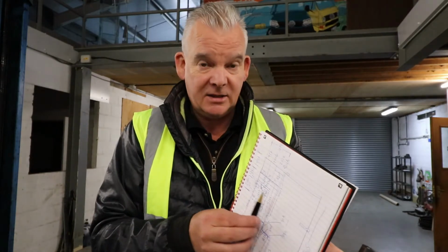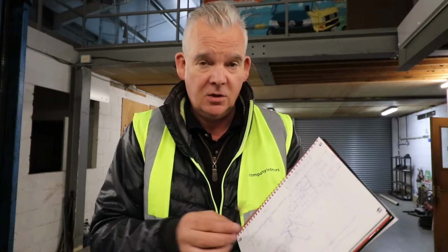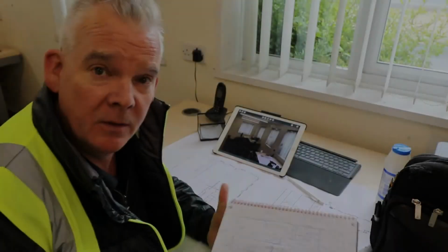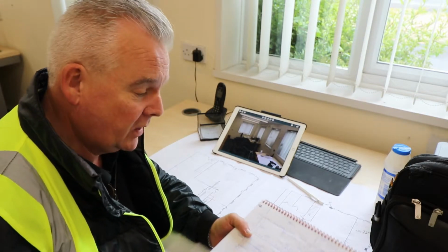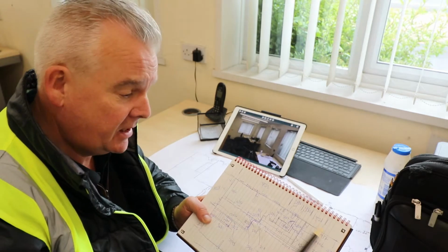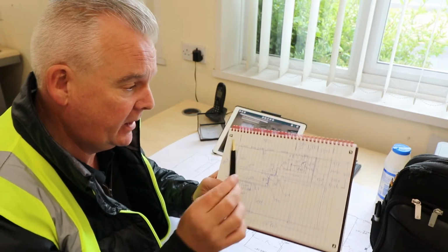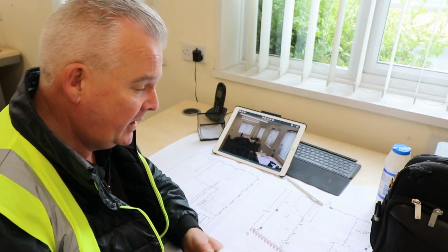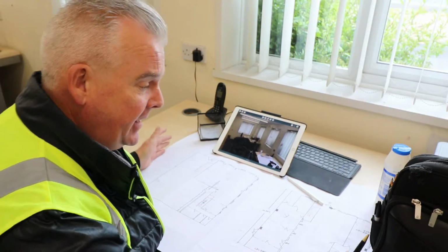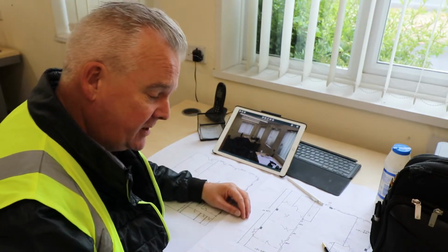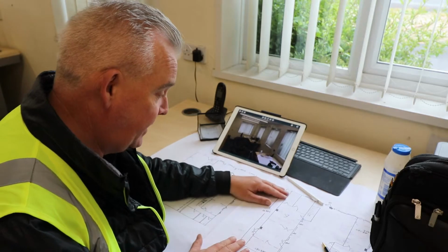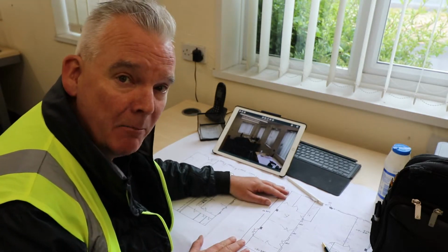We're now just going to go off and we're going to show you how we then correspond that, still manually, with drawings from site, onto a scale drawing before we head back to the office and start getting it CAD'd up. So I've just found ourselves a little vantage point on the site here. What I'm going to show you is, after taking all of the details of the building and putting them on our notebook, what I'd always like to do is take an A1 piece of paper. I like to then have a scale rule, and I like to take these dimensions off of the pad and then actually put them on the drawing manually.